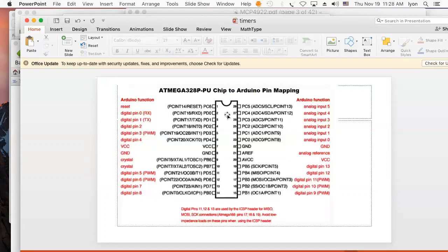One of the things you can see when you go to these different pin numbers is they somehow map to pins on the actual 328P. I think we said it was going to be pin 8. There's digital pin 8, and that's on port B. Then somebody said digital pin 9.